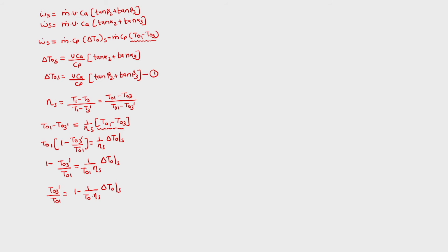But this is P03 upon P01 bracket raised to gamma minus 1 upon gamma, equal to 1 minus delta T0 stage upon T01 into stage efficiency.